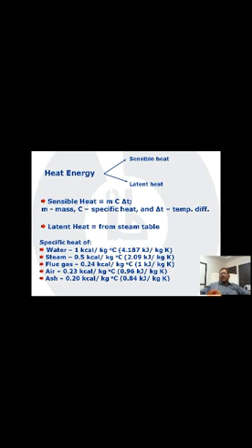This is given in the reference; you can also write it down, right? Water, you can assume as 1 kilocalorie. Steam as half of that. Gas and air, you can take both as about 0.24 kilocalorie, but one is 0.24, another is 0.23. And you may also need the specific heat of ash, particularly for a coal-fired boiler, which is taken as 0.2 kilocalorie.